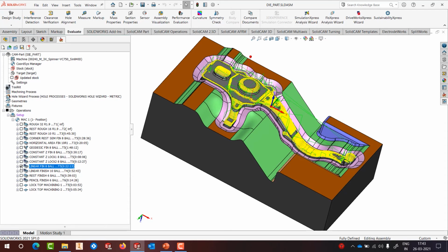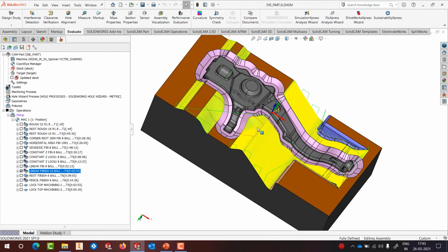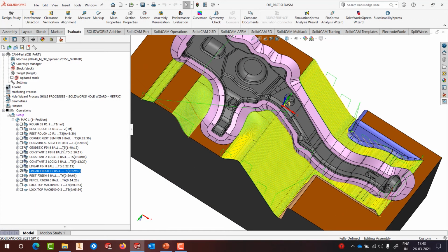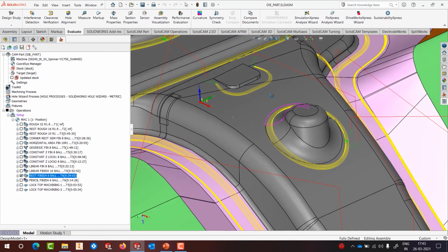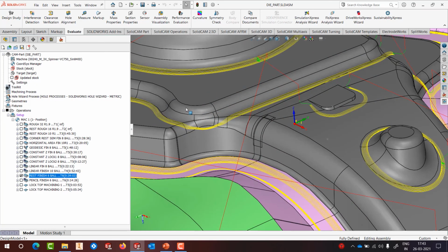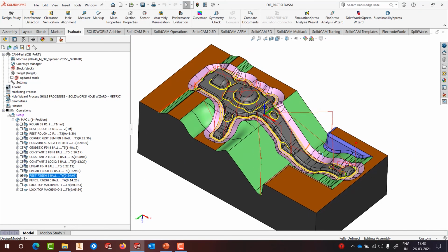Okay, and then the parting surfaces, we have machined using, again, turbo linear machining with 10 ball mills and some rest machining. You can see how nice and smooth the toolpaths are using HSM's rest machining. So I have used a combination here. Majority of that is being generated by turbo machining technologies, while in between certain regions I'm using the HSM toolpaths also. I'm running finally with the pencil machining functionality in turbo machining. We've got the pencil machining functionality, and that just goes around all the corners.